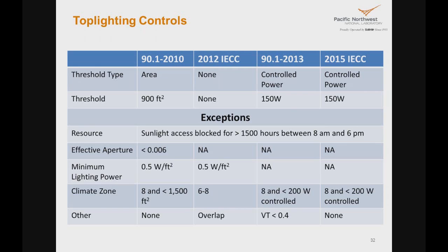Yeah, so it might happen that in a large or open office, your daylight area extends a certain amount, and there is just one fixture, like half of the fixture, that falls in there, which makes you go over the threshold. There may be some situations like that, but they should be rare, and they should be explainable with the code official.